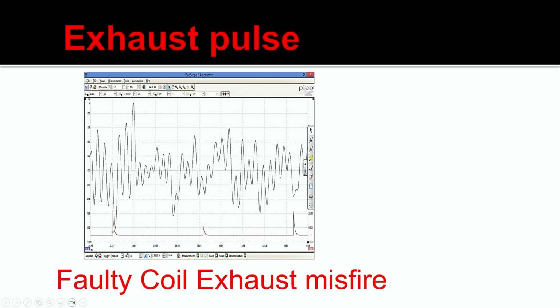And I can do the same thing by hooking up to a vacuum hose, and a vacuum hose is going to, in essence, give me a cylinder leakage type of test result because I'm seeing the opening and closing of those intake and exhaust valves. Again, the first test is just hook the pressure transducer up. One channel, quick go or no go. If I'm getting uniform results across the screen, I'm good. I'm going on to the next test.